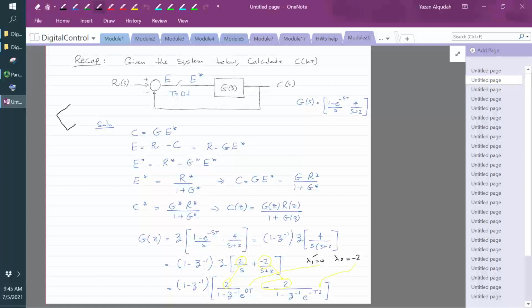I'm going to have a microcontroller. Let's say this system that we're trying to control is a motor. So this is my motor. I'm taking the position, for instance, of this motor, and I'm subtracting it from the signal that I want to apply. So I have a knob, or a potentiometer, that I can set the position of the system.